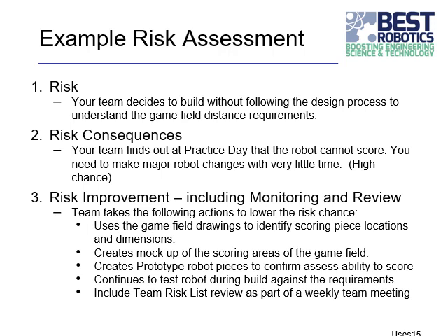So how do you avoid having that happen? Well, obviously you need to look at the game field drawings as you consider how big things are and how far away. You need to have those understood and identify those as requirements. We talked about having a mock-up of the scoring areas of the game field, either with tape or cardboard or pieces of spare wood, or actually build a game field. You need to create that prototype before you start cutting wood. If you cut wood and you haven't considered the size of the field, you can be faced with having to purchase additional materials beyond what we gave you in your kit.